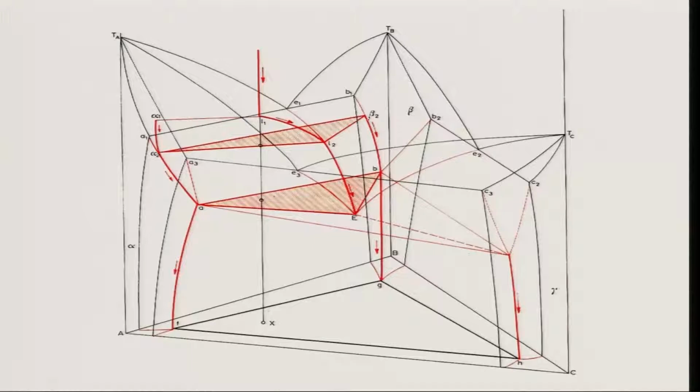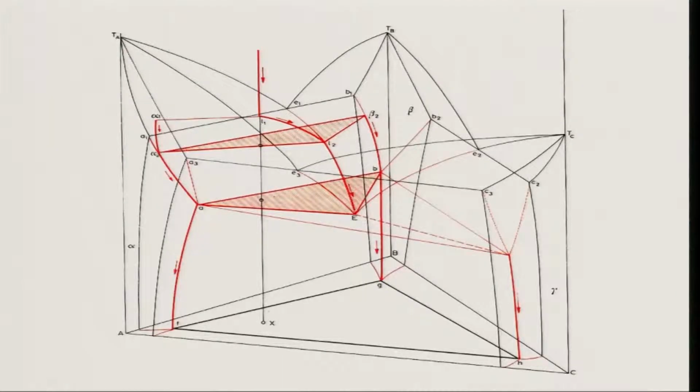Obviously, the first one is the alloy composition corresponding to point capital E, and this will lead to the formation of only ternary eutectic between alpha plus beta plus gamma. That is easy to understand. The second one is alloy composition lying on the invariant, monovariant rather, liquidus curves like E1E, the one is this curve, you can see the red mark given, or E2E, E3E.